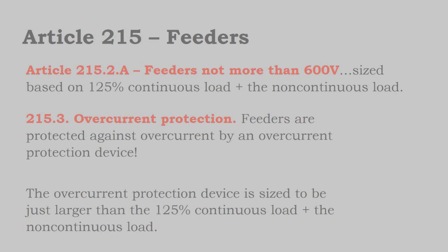So there may be a requirement for an engineering calculation. There may be a requirement for rigid metal conduit. There may be a requirement for, I don't know, additional protective relays. You also gain some cost efficiencies of using higher voltage equipment, and so that's great too. So when you get into higher voltage equipment, there are perhaps some cost savings on the overall system, even though individual components you're spending more money on, and you'd have to buy different things for higher voltage commercial systems.